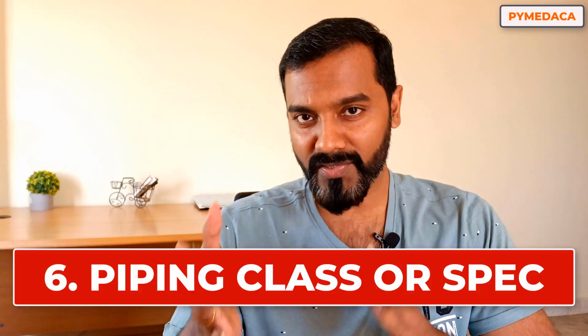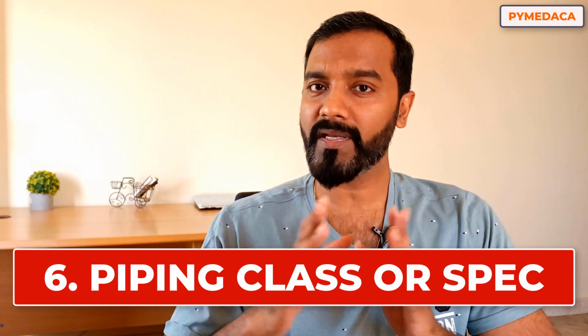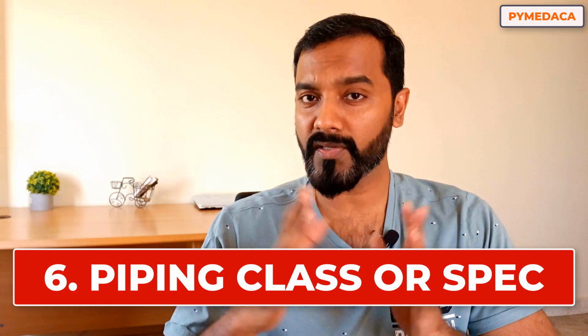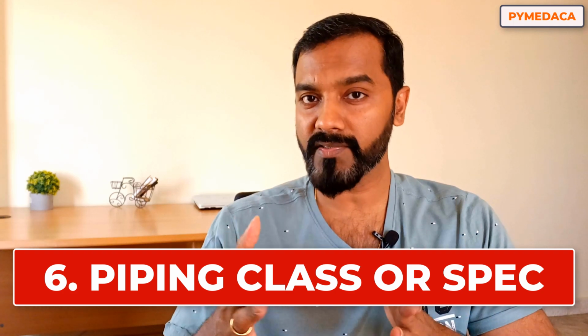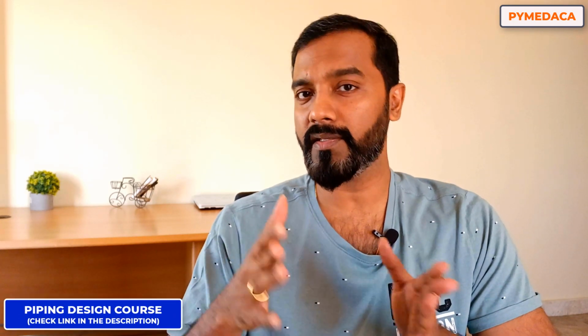Piping class is the next document that you need to have. Piping class is nothing but segregation of standardized piping components, where you will find the pipes, fittings, valves, bolts and gaskets for a particular temperature and pressure range. So this document is standardized in such a way that you will be able to use a particular component in any line which applies within this temperature and pressure range.